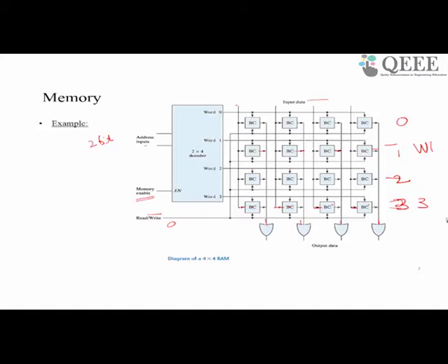for which we need a decoder which is a 10 to 1024 decoder. Now let us look at the complexity of constructing a 10 to 1024 decoder. It should have 1024 AND gates, each of which has to be a 10 input AND gate. So the complexity of the decoder is very large. And this is just for 1K. If you are going for 64K or 1 MB, then it becomes impossible to have such kinds of decoders.